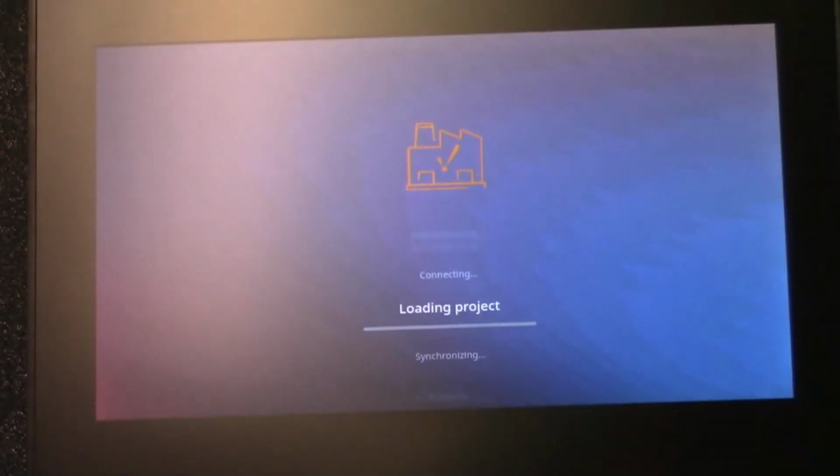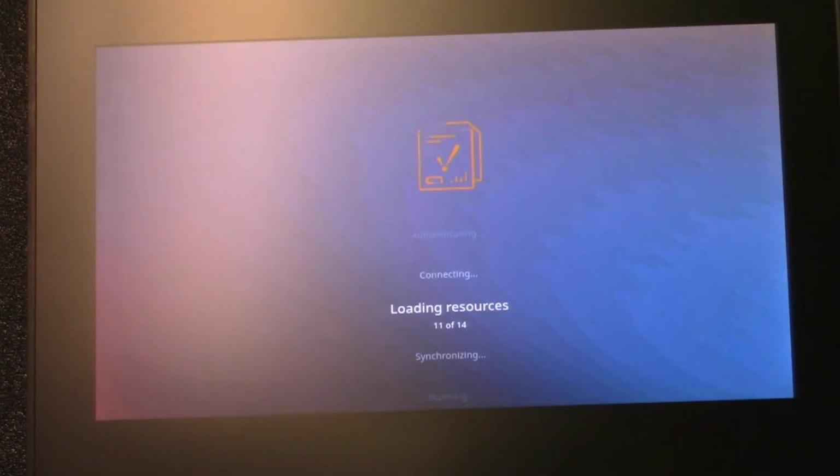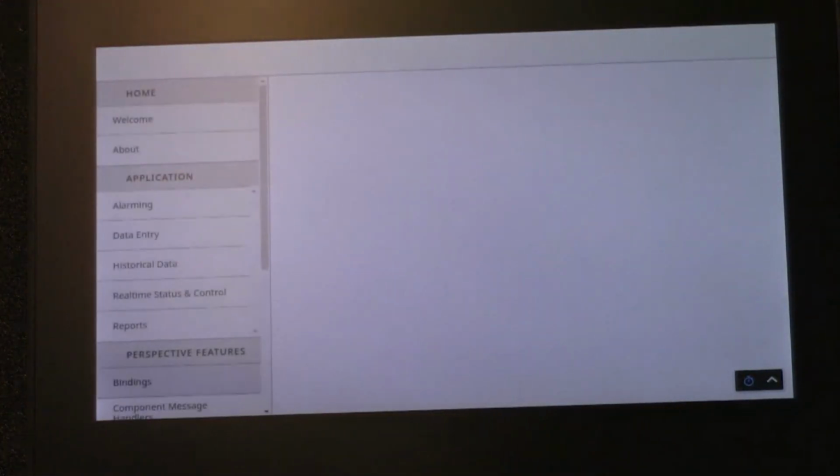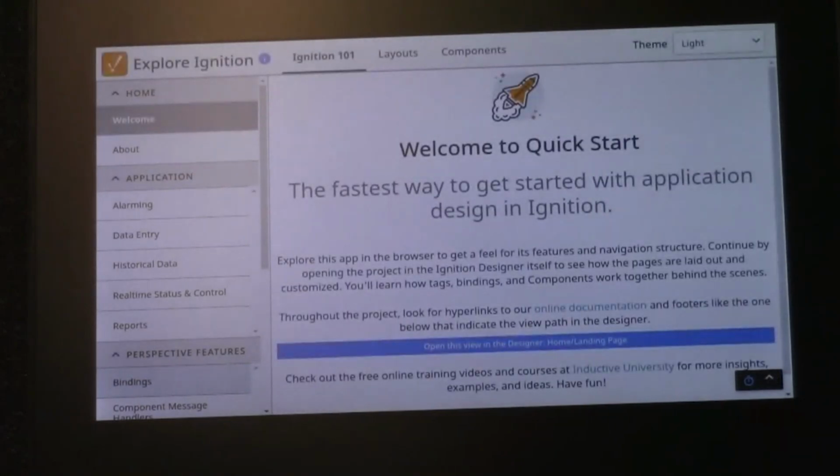And remember, as I've mentioned, and I really want to hammer down, these devices are not just display-only devices. So the web HMIs don't just show the screen that someone else is looking at. It allows you to operate everything on the screen that you would normally be able to operate on the host machine. So in this case, if we are hosting this from an IPC or an industrial panel, we're not just broadcasting what the operator's seeing in a different room. We are able to fully control a separate instance of that screen.